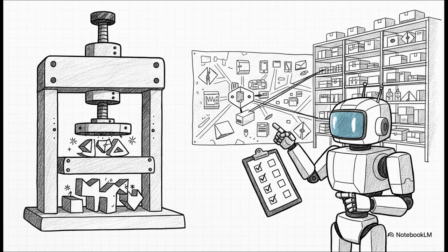And this perfectly illustrates the crazy depth of parallel processing here. Think about it. While the CALU is busy sweating over that heavy math, who is figuring out where the next piece of data actually lives in memory? Well, that's the job of the Auxiliary Register Arithmetic Unit, or ARAU. It manages all the addressing logistics, stuff like indirect addressing, block moves, and auto increments, utilizing its 8 auxiliary registers. Because the ARAU handles all the address tracking, the CALU is 100% free to just focus on pure, uninterrupted math.